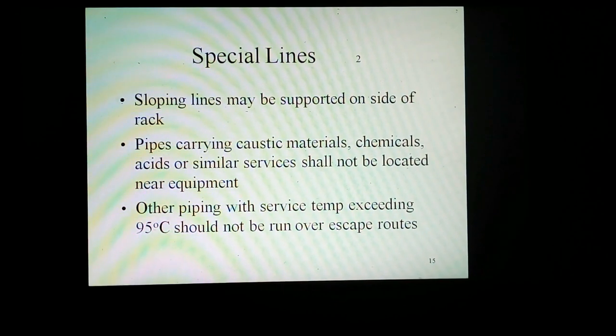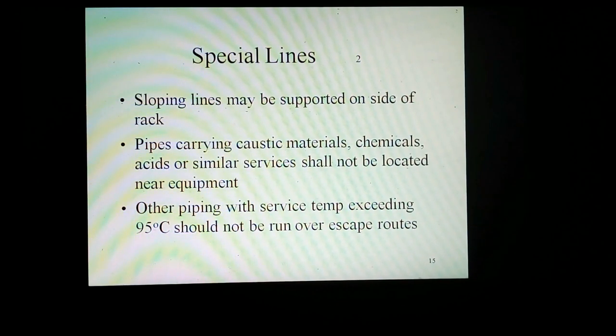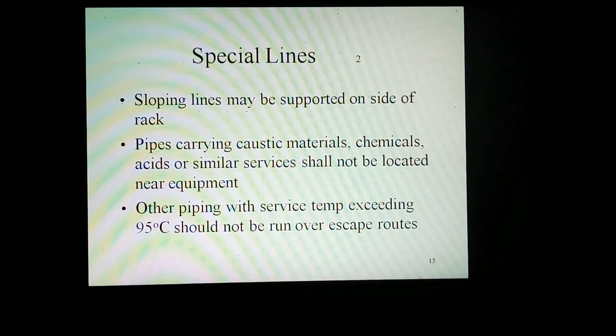Special lines. Sloping lines may be supported on the side of the rack. Piping carrying caustic materials, chemicals, acids or similar services shall not be located near equipment or other piping with service temperatures exceeding 95 degrees centigrade, and where avoidable should not be run over skid routes.